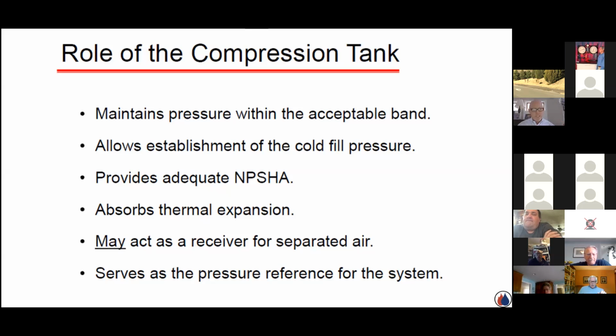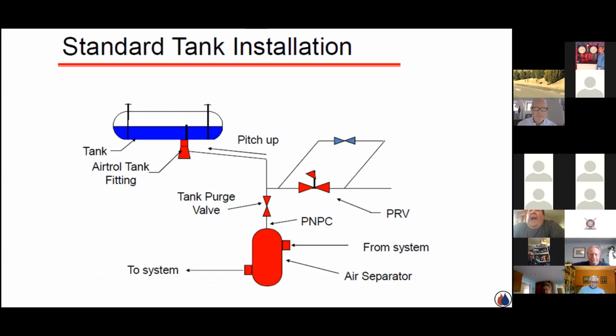That's that old style compression tank. And like we talked about, serves as the pressure reference, the point of no pressure change. Wherever that body of gas is located, the pump in your system wants to reference that point. We always want to pump away from that expansion tank.